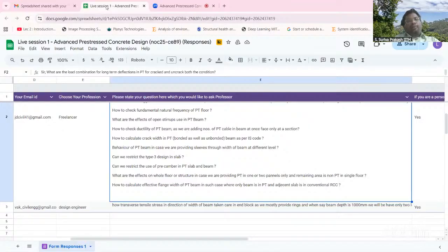Okay. Now, I think your inputs are very good. So what we will do is, in the next part of the module, the next year's offering, we will also record some example problems for how to calculate that, and then we will add it as a part of the course module. Because typically, in pre-stress, we don't want to have crack widths at service, right? Even if you go back to the moment curvature analysis that we have talked about, your cracking moment and yielding moment will be very close to each other, right? So if your system is cracked, then you lose all the benefits of pre-stressing.